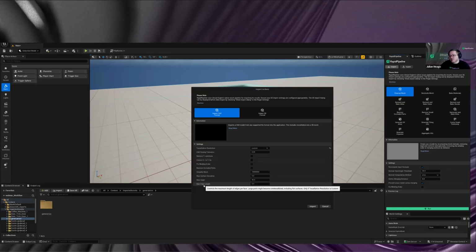This is usually very helpful for shading or other workflows which deal better with a more homogeneous topology rather than a very heterogeneous one where you only have highly tessellated corners and very flat surfaces, which is in itself also not bad. But sometimes, especially with the mesh normals, you might run into problems. So this can help. We have other settings such as removal of T-junctions.